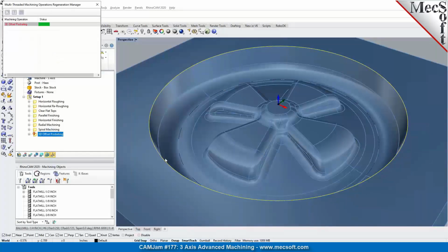Now this toolpath method, as mentioned, generates a constant 3D step over, also known as uniform 3D step over, or constant scallop machining. So when you have steep sections and flat or near shallow areas, or I would say freeform or sculpted bottoms, it maintains a constant 3D step over.